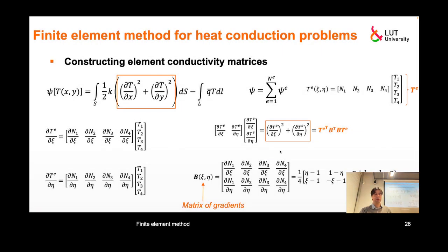I calculated all those partial derivatives. I factored out this 1/4, and I have this matrix with components depending on local coordinates. In this case, it's linear because we are using linear interpolation, linear finite elements. So it may be non-linear if you're using higher order elements, of course, but you can still calculate it. This is our gradient matrix. We actually know it.